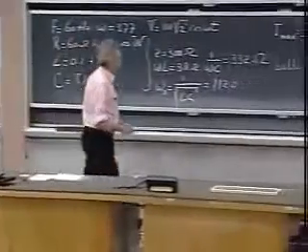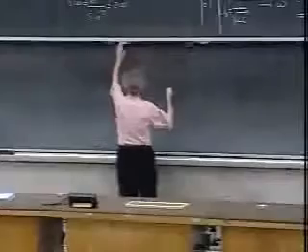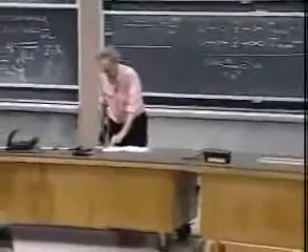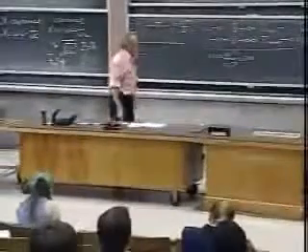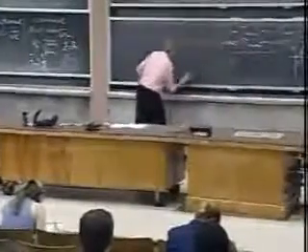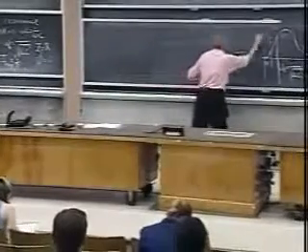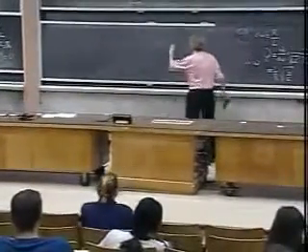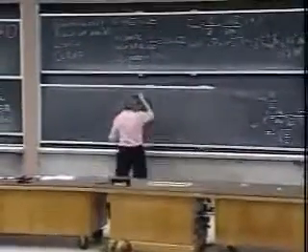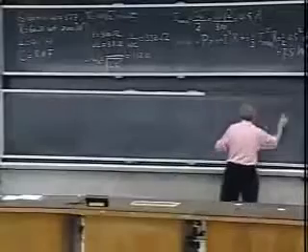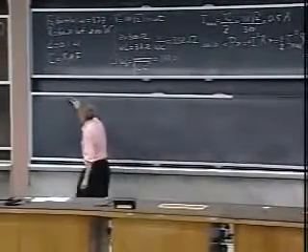Great. So now comes the question, what could we do to get the system back on resonance? Well, we know that our driving frequency is 377 radians per second. And so what we could do, we could change the C in the circuit, and we could change L in the circuit. If we make L larger or make C larger, then obviously you shift your resonance frequency down from 1120. And my goal is to shift it down to 377 radians per second.